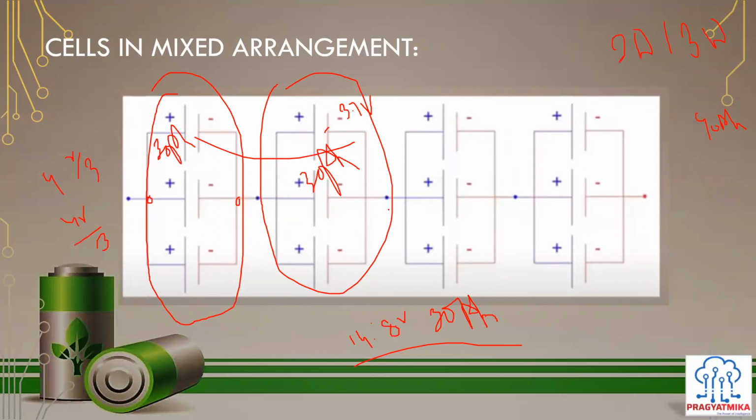No, because this will mislead it, because there are 3 cells connected in parallel. So even if this cell gets open circuit, or if this cell's capacity is fading faster compared to the other 2, there is no impact on the potential. Even if this cell has gone bad, the potential would remain the same, and we will not be able to figure out which cell is going bad.